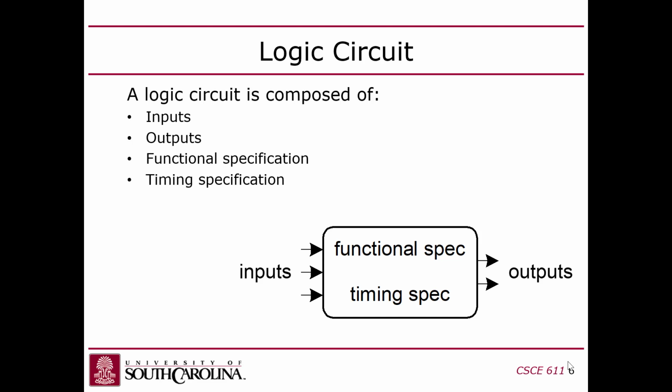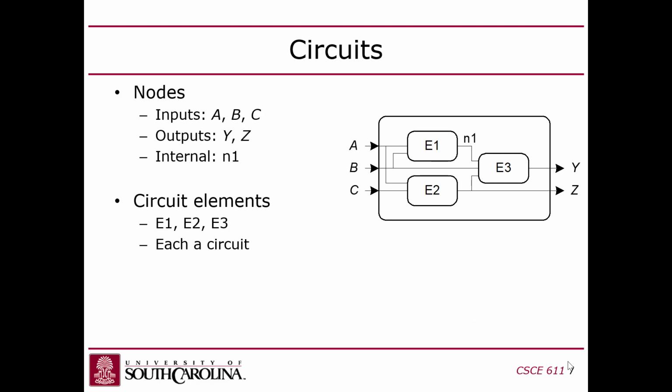For you to design a logic circuit, you have to think of it like drilling down inside and opening up the hood to see what's inside. Inside a logic circuit, you have logic elements that are generally logic gates or LUTs. And then they're connected both to the inputs and outputs, as well as, in some cases, to internal wires that are not visible outside the circuit. If you think of an object-oriented language, I like to think of these as kind of like private members in a class. They're not visible outside, but they're inside.